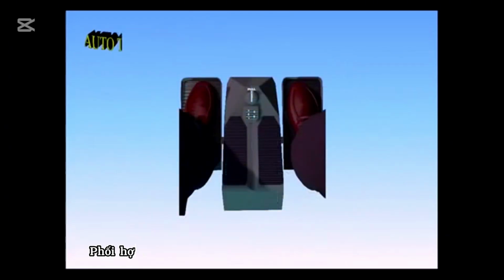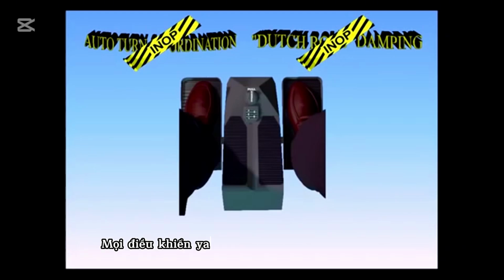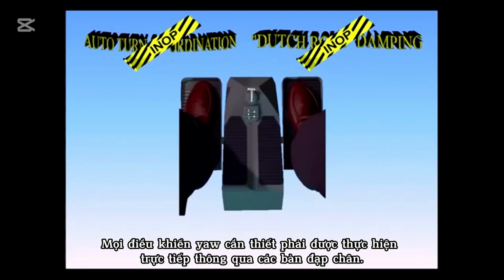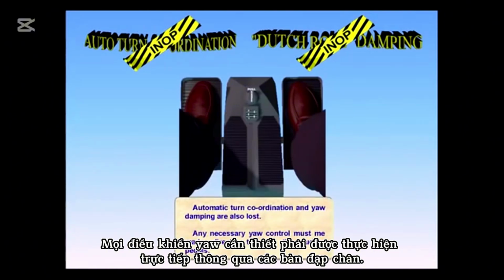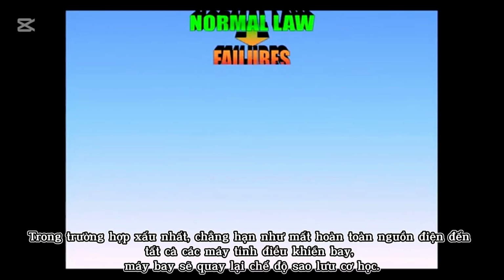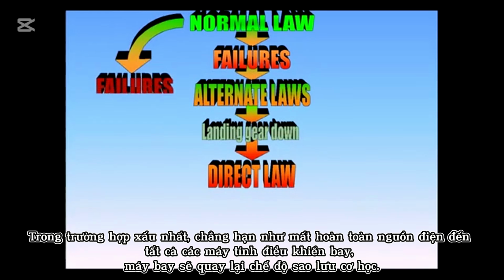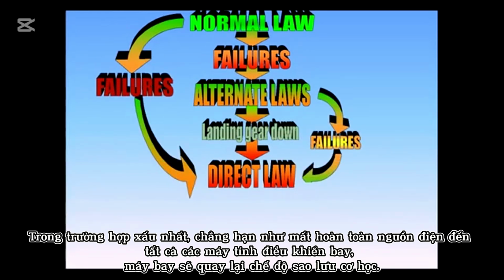Automatic turn coordination and yaw damping are also lost. Any necessary yaw control must be made directly through the rudder pedals. In the worst-case scenario, such as complete loss of power to all flight control computers, the aircraft will revert to mechanical backup mode.